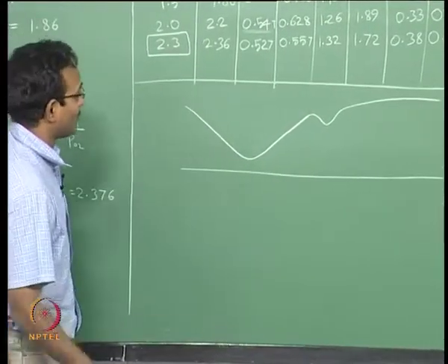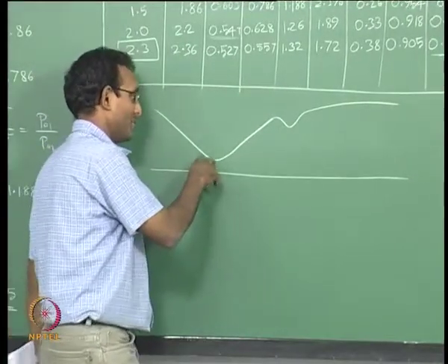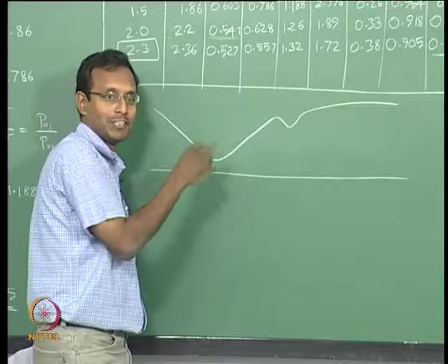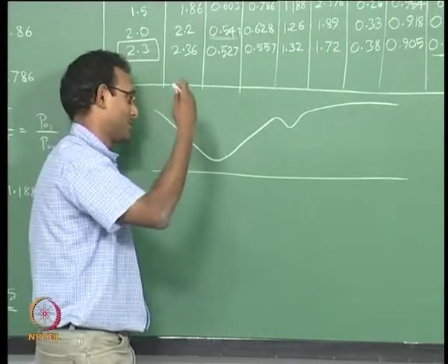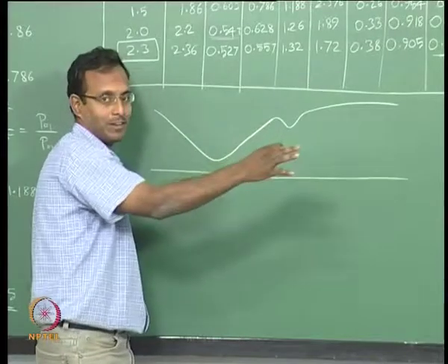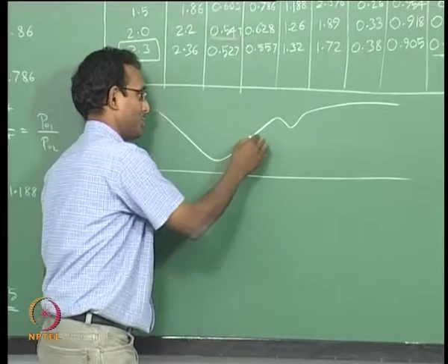How will I solve this problem? If it is a fully subsonic solution, I am going to say it is going to go through as A by A star. I am assuming it is choked here. If not, you can also solve the problem similar to what we talked about last class towards the end. The same procedure can be applied here. That is not interesting enough. So we will go to a case where there is a shock in the divergent section.